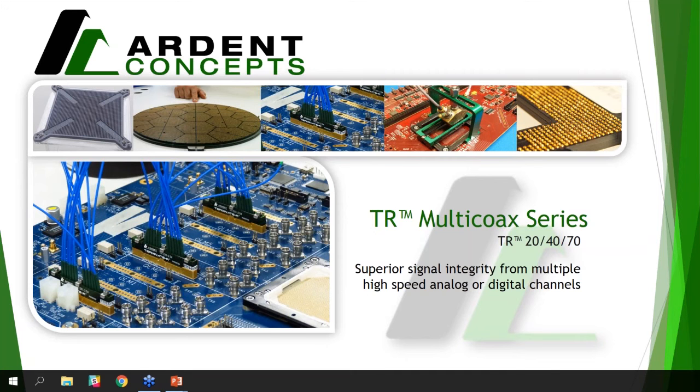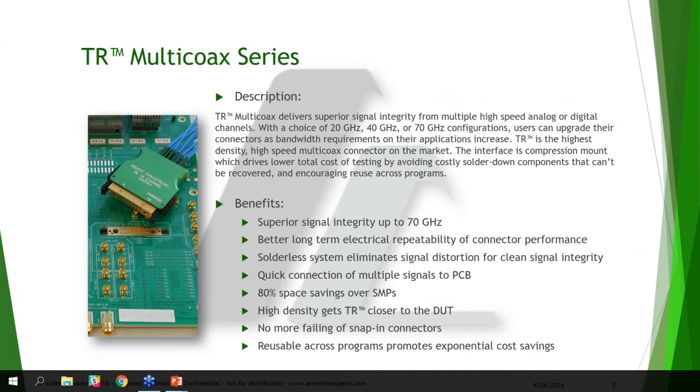I wanted to mention that at the onset of this product, we called it Terminate-R, and TR is synonymous with that. So you may hear me refer to it as Terminator in certain cases, as it's printed on the molded parts that we make, but TR and Terminator are the same thing. So when we started out to develop the Terminator, signal integrity was the most important thing to us. We have a very, very short interconnect, and we wanted to take advantage of that and make sure that we can translate that super short interconnect into very high bandwidth capabilities.